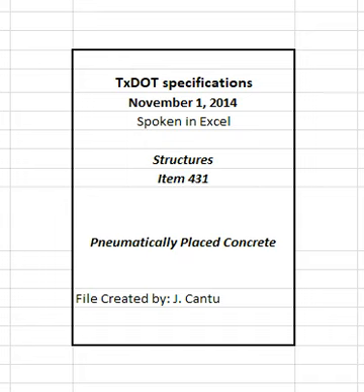This price is full compensation for cement, aggregate, water, and reinforcement, furnishing and installing steel anchors, removal of deteriorated or unsound concrete, mixing, placing, and curing pneumatically placed concrete, and equipment, labor, tools, and incidentals. Pneumatically placed concrete used for work other than encasement or repair will not be paid for directly but will be considered subsidiary to pertinent items.